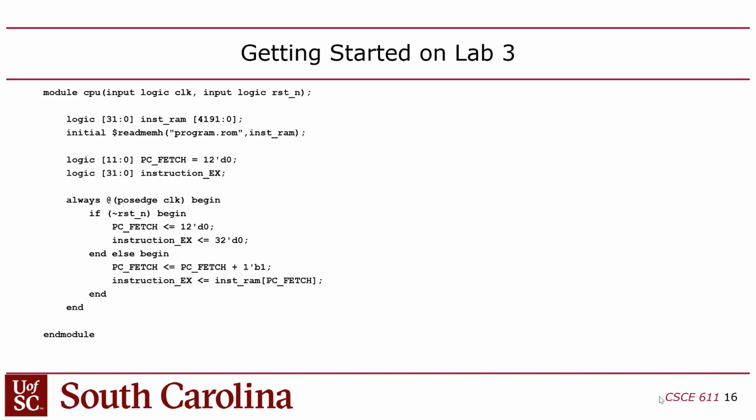It's going to give you an instruction sequence. So you're going to get a stream of instructions once per clock cycle, right? And that's what we expect to start with. Once we have that, then you guys can bolt stuff onto that. You can put control logic on there. You can connect the instructions coming into your ALU and your register file. It's real easy, but you've got to start out with a stream of instructions.